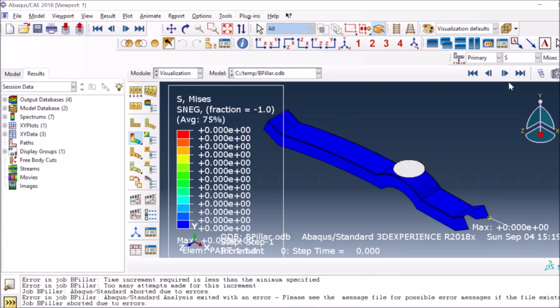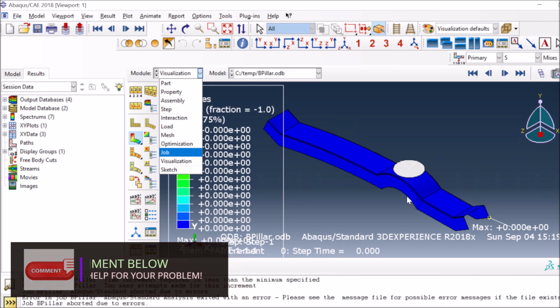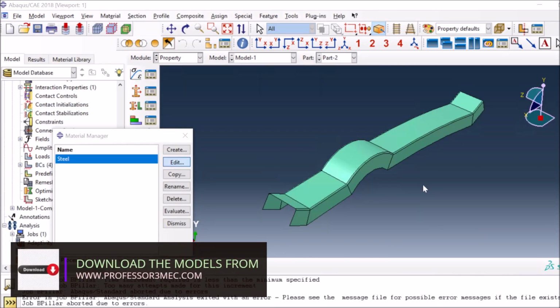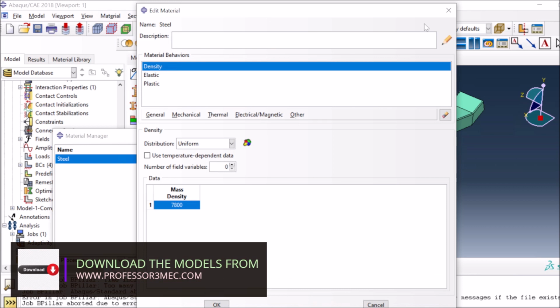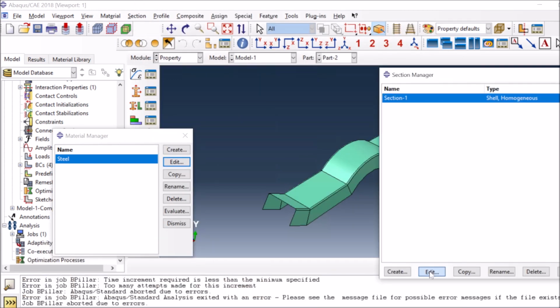So what you see here is it didn't write anything, but it might be the case that the thickness is too large, that it is going out of this. As I told you, we use middle surface, so it distributes the thickness bottom and top, and that might have been causing problems. So I'm gonna go back and I'm gonna change the thickness to a limited value.